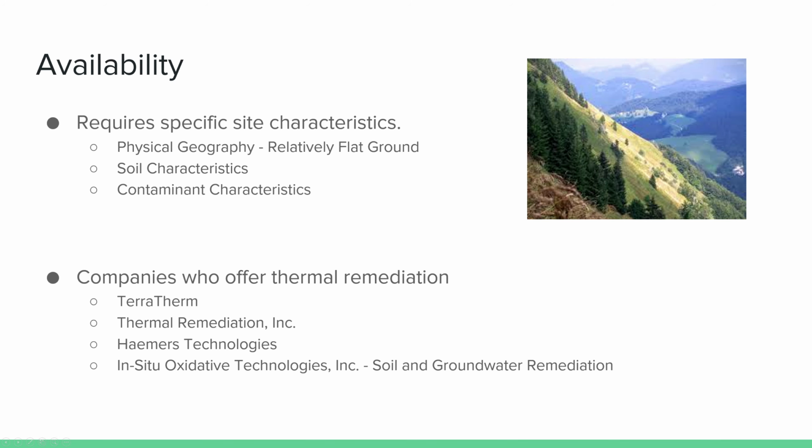The availability of thermal remediation largely depends on your specific site characteristics, such as the physical geography, the soil characteristics, as well as the contaminant characteristics. And if your remediation project doesn't involve the exact site characteristics that thermal remediation requires, this will not be an option that's available to you. Therefore, your availability is quite low.